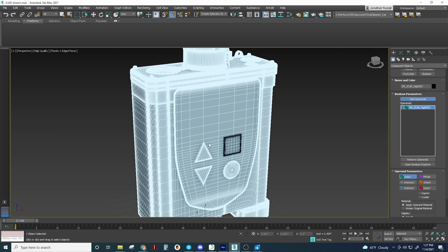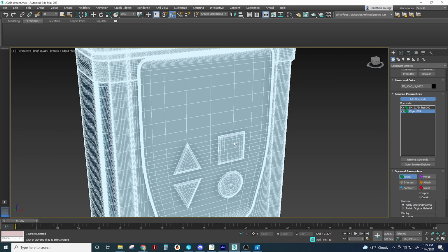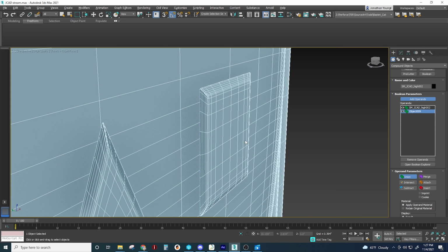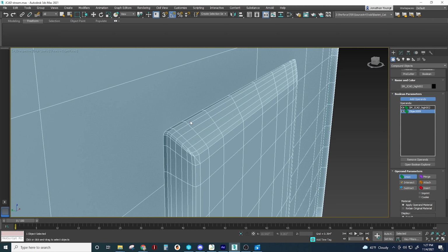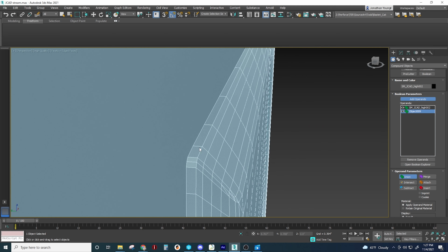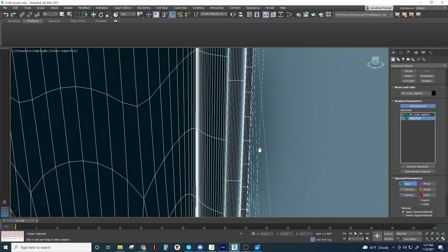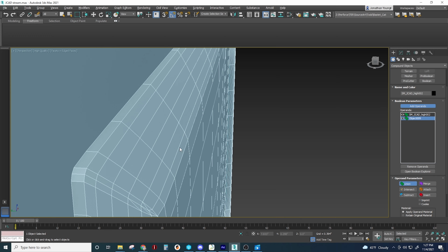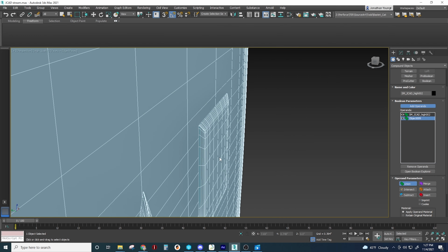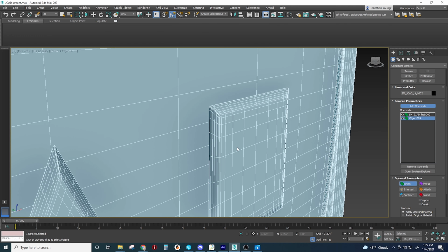So I'm going to add operand, and then select that button. Okay, and it added it there. So now you can see that this button has actually been unioned to the face of this object. So if I go along to the back here, there's nothing protruding inside anymore, and it's attached.